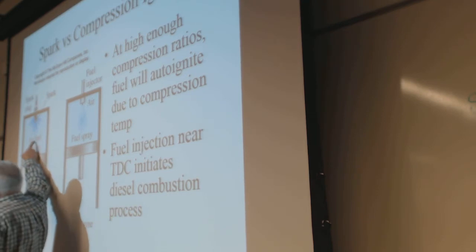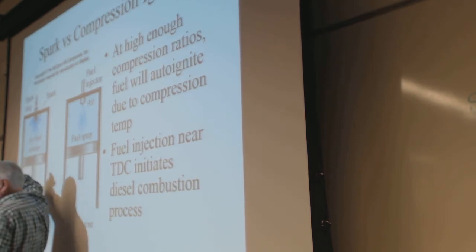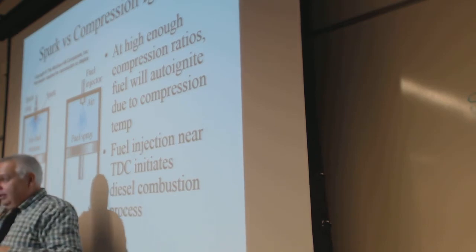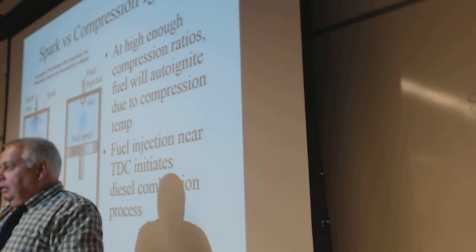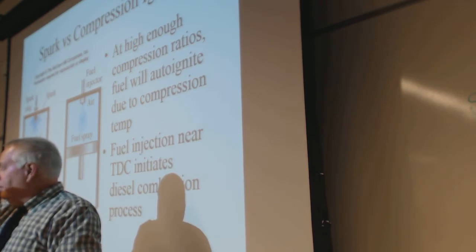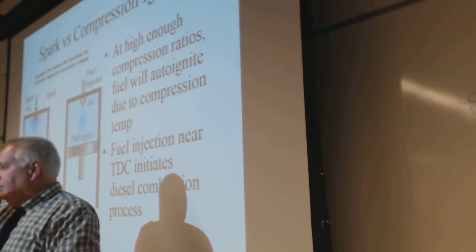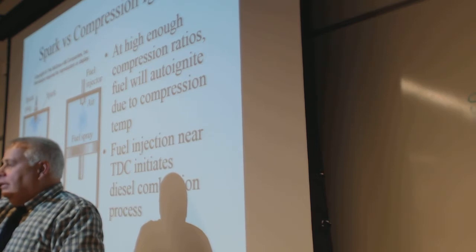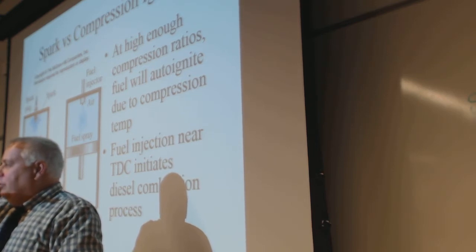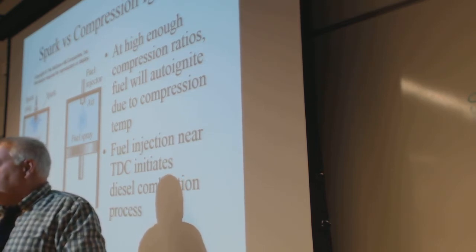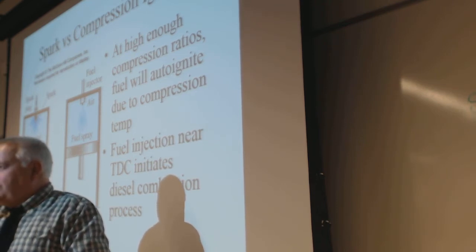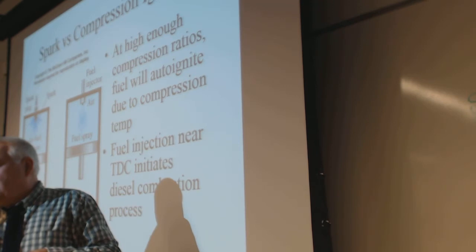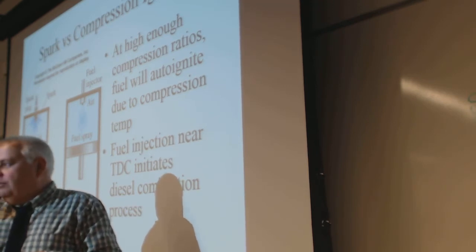You control the mass in here by making it a vacuum. So they have manifold vacuum. Anyone ever have a car that has the gauges, so they'll actually measure when you're idling, it'll be at, I mean, a hippie-inducing vacuum. And when you go full throttle, it comes up almost to atmospheric pressure. If you get a supercharger, it'll go above atmospheric pressure on the inlet manifold.